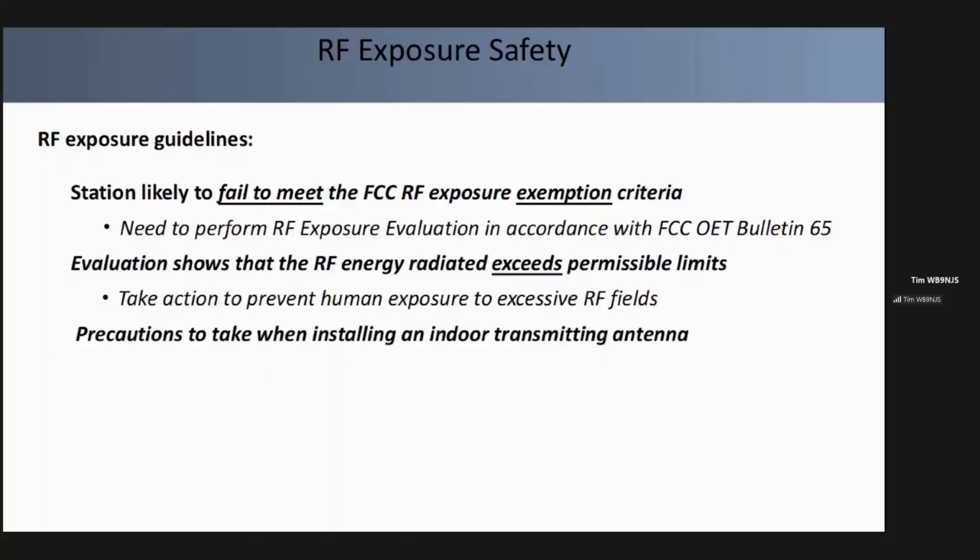So if you are going to install an indoor transmitting antenna, you must make sure that the MPE, that's maximum permissible exposure limits, are not exceeded in occupied areas. So precautions when installing an indoor transmitting antenna: make sure the MPE limits are not exceeded in the occupied areas.